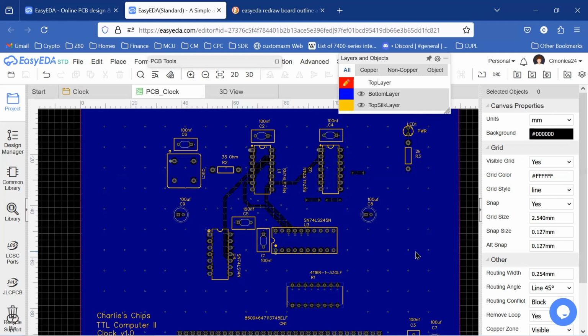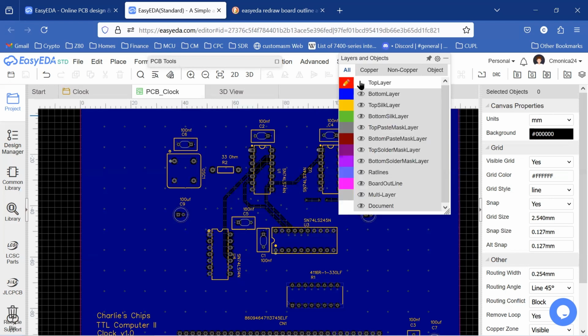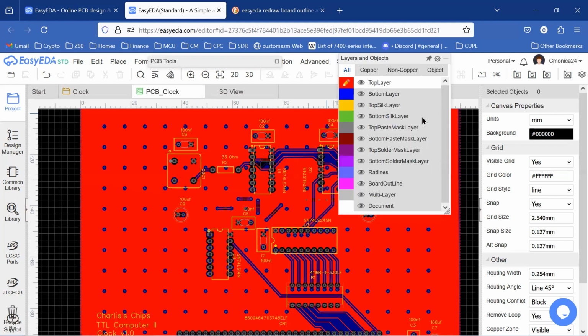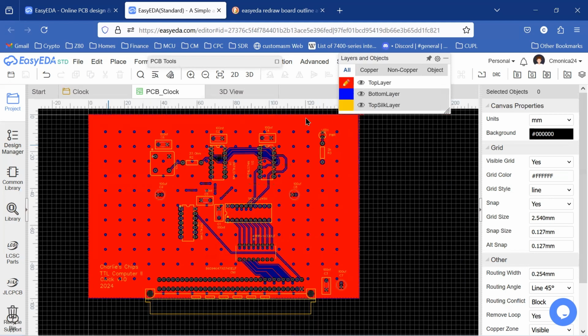That's desirable. Let's go back to our top layer here, and the red layer is another copper pour, and this copper pour is for VCC, and this provides our power plane. So we kind of have a sandwich. We have our board in the middle. On the top layer, we have a power plane, and on the bottom layer, we have our ground plane, and those two things kind of make a big capacitor.